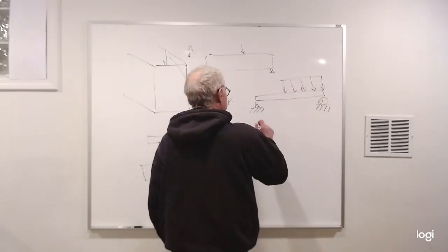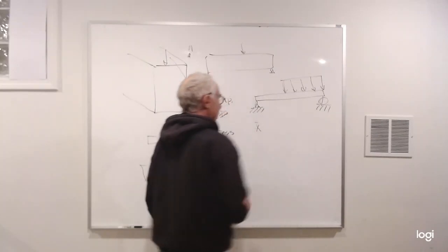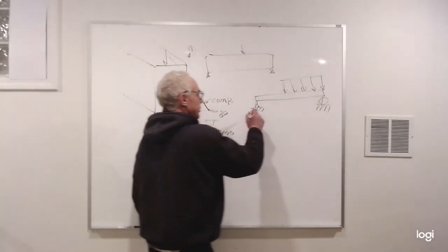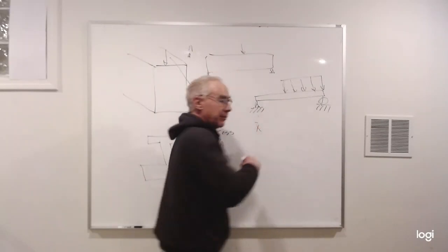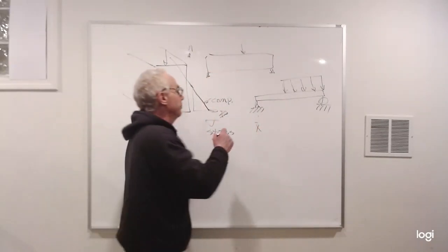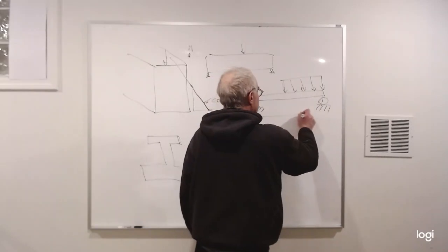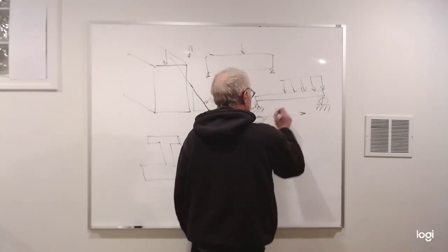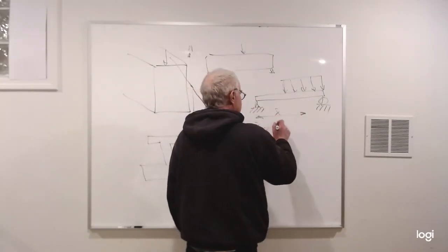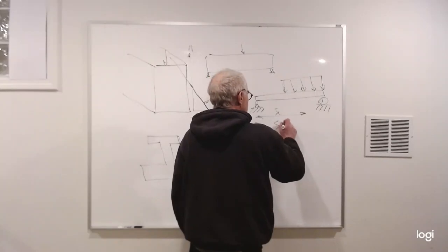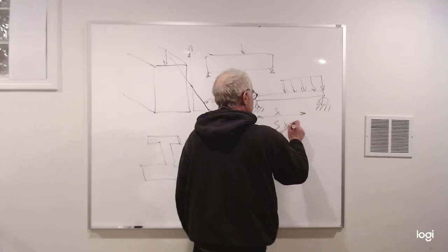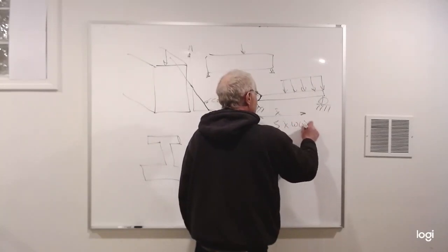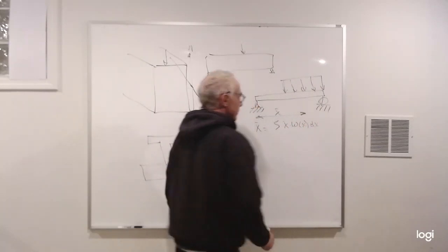And what we said is that centroid x bar, and that would be measured, well, you could measure it from wherever you want, but typically we measured from the left-hand side of the board. That would go to here. And we said that that's equal to the moment x times w of x dx.